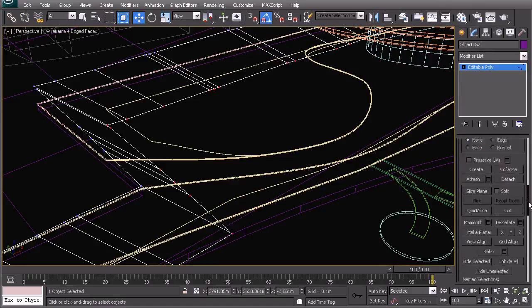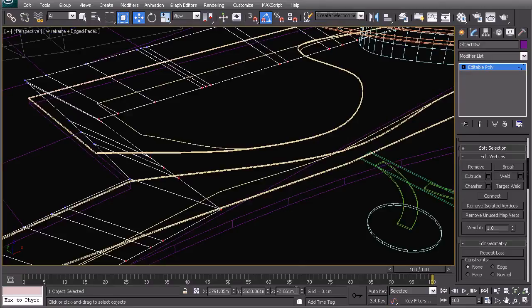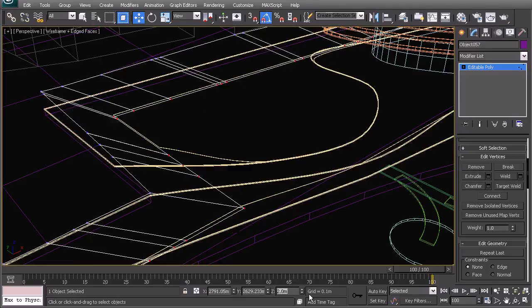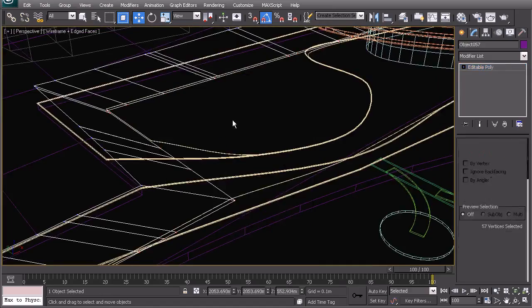First, before we do that, let's just move them all planar in Z. And then let's move this number to 2 meters. Just get that right. So if we have a look now, they're all sitting at the right plane.